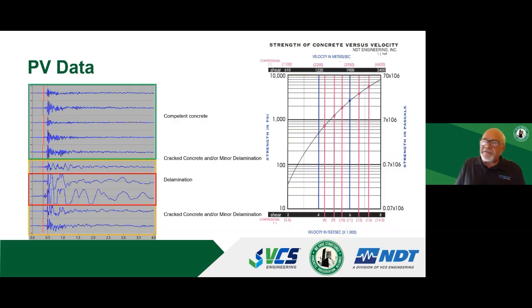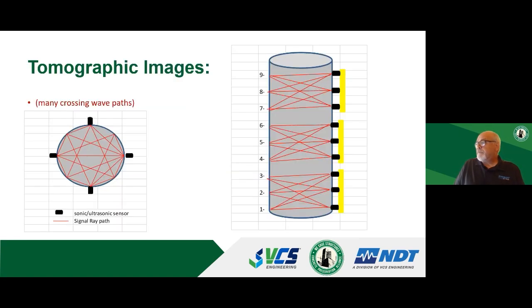You're taking that core out of its element, so let's remember that. When we record information on a beam or a column or a deck, we're doing it in situ and more representative of the internal stresses that might be acting on the midpoint of the beam or in the deck or in the bay of the deck between the girders. So I might argue our number is a little more representative as opposed to you take a core out of its element, ship it to a lab and trim it and break it, but they do correlate very, very well.